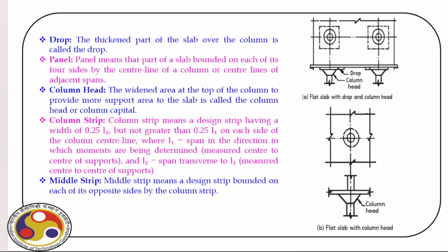Now, when we design this, a couple of things we have to keep in mind. The drop panel, obviously, at this portion, is much thicker compared to the slab thickness, which is here. Now, when we have, say, two supports, as you can see here in plan, then this slab, the flat slab, behaves like a plate, and there will be two critical regions.